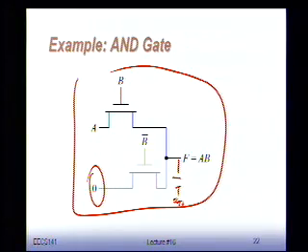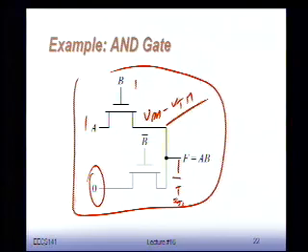Yes? It never gets up to VDD. That's right, you get a threshold loss, because this is only NMOS transistors. If I want to pass, if this is 1 and this is 1, I'm going to get VDD minus VTH here. So who cares, a little bit of a VTH loss? Actually, it's reduced swing, it's less power, so it's actually a good feature.